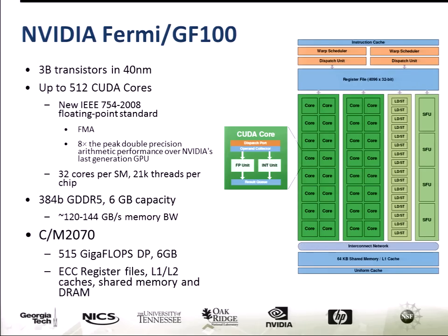So I'm not going to dive down into this in too much detail, but the architecture of this is important. It's important to understand why things are going this way. They've created all of these simple cores, and these aren't cores in the terms of an x86. They don't run Linux. They can't run a lot of things that a normal x86 core can run. But they're very good. They can load, thread, execute a few floating point operations, do a few load and store operations, and then basically be retired. And you have hundreds or thousands of these potentially on a GPU chip in and of itself.